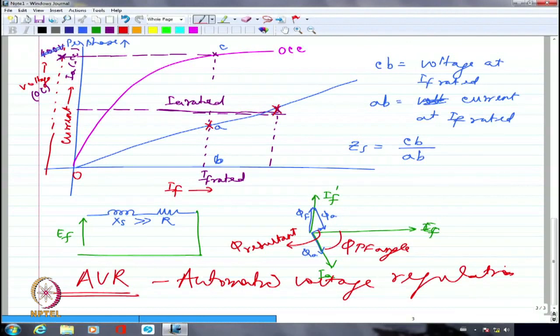That's not possible. The same way, in the short circuit condition, obviously the voltage that I would measure across the terminals of the armature will be zero because I have short circuited. So, I don't have a way to measure the armature voltage. So, that is the reason it's a very, very beautiful method, whoever has devised it, to get what is the voltage that would have been generated in the armature under open circuit condition, vis-a-vis what is the current that is being drawn by the armature had it been short circuited with that kind of generated voltage. So, very clearly, there is a huge amount of difference between transformer circuits and synchronous generator circuits, the equivalent circuit as well as the way it is being analyzed. So that is the reason why they are quite different. Okay?